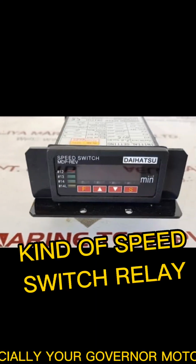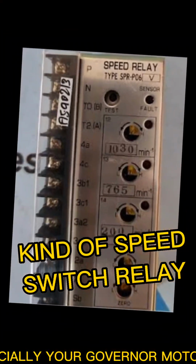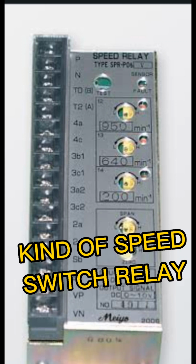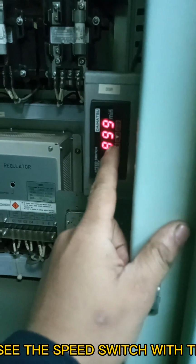The overspeed trip testing method I will show you is easier and safer, especially for your governor motor safety, if your generator system has a speed switch sensor like you will see in this video. This time I will show you how to test auxiliary engine overspeed using a speed switch. When you open your panel, you will see the speed switch with the display of the actual RPM of your engine.